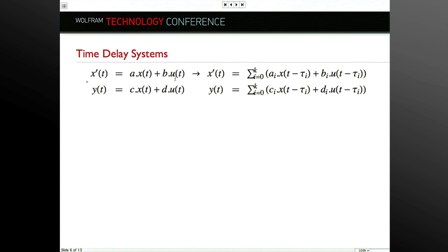All right. So the second extension that we have is time delays. Once again, we've expanded what our differential equations can support. Here, instead of just having the states x of t and the inputs u of t, you have these x of t minus tau and u of t minus tau. Those taus are delays in the system. And we can take these in state space models or transfer function models pretty much anywhere in the system, and work with time delays.